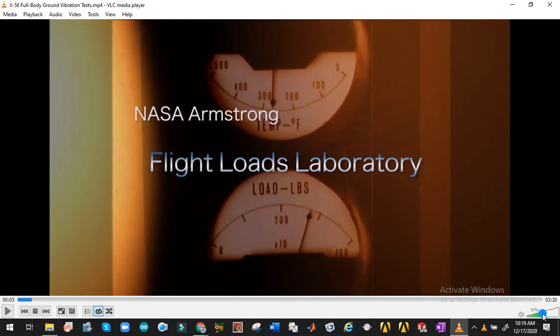There are three possible ways. One is we can solve an analytical model and derive the mode shapes. The second way is to solve the system in a simulation environment, and the third way is to solve the system in an experimental environment. So analytically we will solve possible types of problems. In case of simulation, as we are doing the ANSYS lab as well, I will show you how an aircraft wing vibrates at certain modes, what natural frequency a particular mode is excited at, and how we can find the multiple mode shapes using ANSYS.